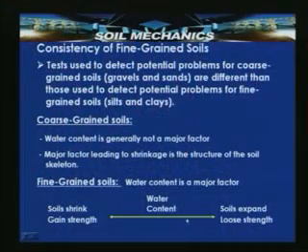For fine grained soils, water content is a major factor. If you see here, as the water content increases from left to right, soil expands and loses strength. As the water content decreases from right to left, soil shrinks and gains strength. So, fine grained soils are prone to be affected by the presence of water.